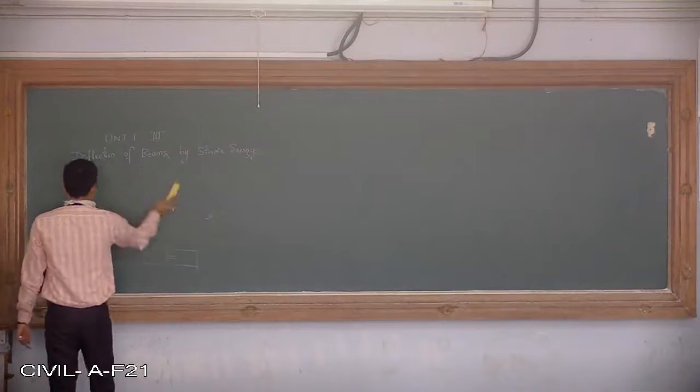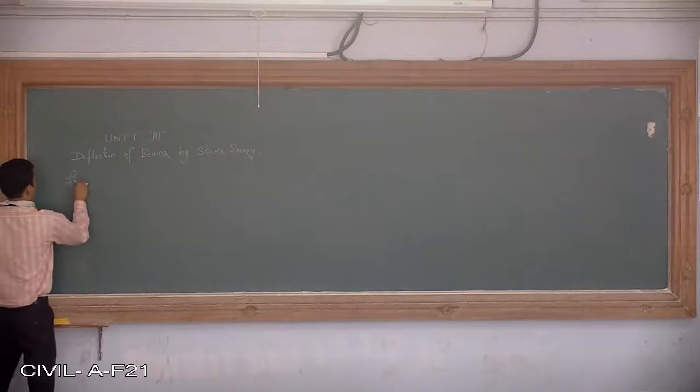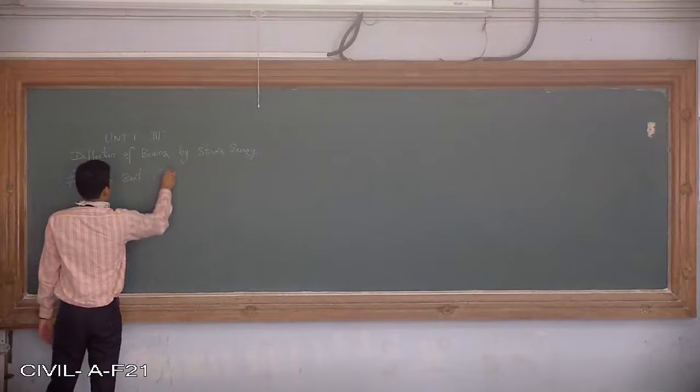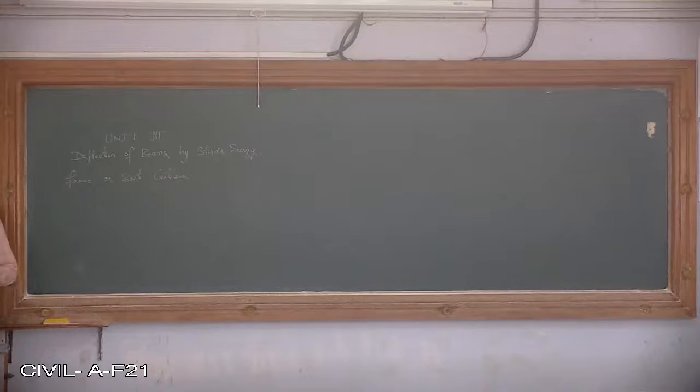So beams, we have already completed with point load and UDL. The left part is a frame, or it is called a bent cantilever. Numericals on deflection of beam are finding the strain energy deflection, that is vertical deflection as well as horizontal deflection in bent cantilevers. So one standard case I'll take so that it is clear how you are going to take vertical deflection and horizontal deflection. Later we'll have a combination of horizontal and vertical deflection.